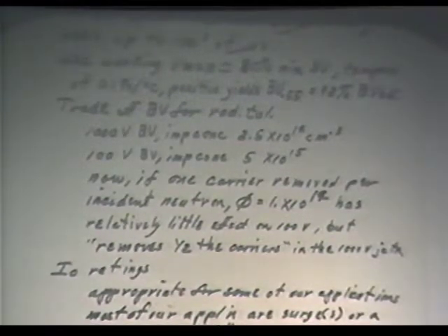And again, I did an arm wave here for trying not to exceed 80% of breakdown if you have the luxury and the environment permits it and all that sort of thing. Hit you again with the temperature coefficient being positive, which hurts you at cold temp. And you can trade off, generally, everything else being equal, breakdown voltage capability for radiation tolerance. First approximation. The higher the breakdown voltage, everything else being equal, the higher the resistivity of the material will be, and the more it will suffer from neutron damage.